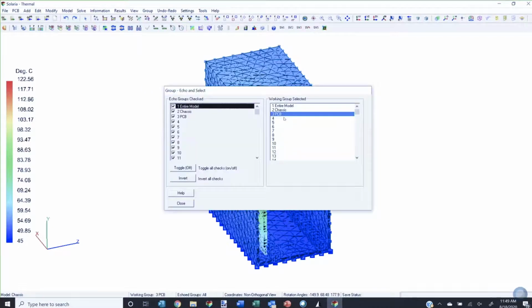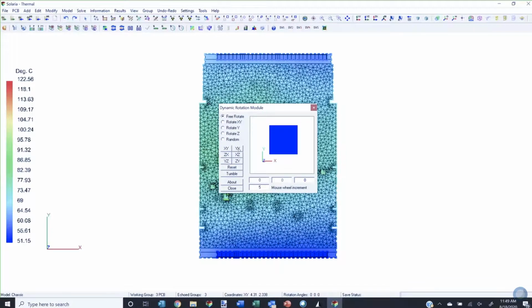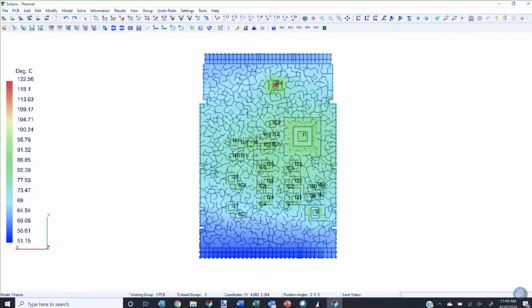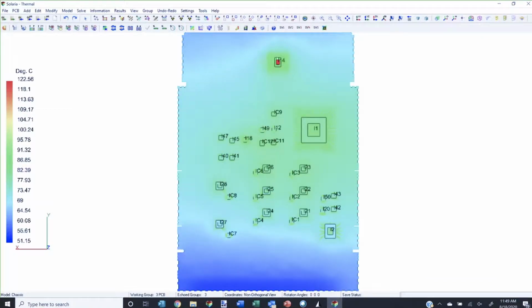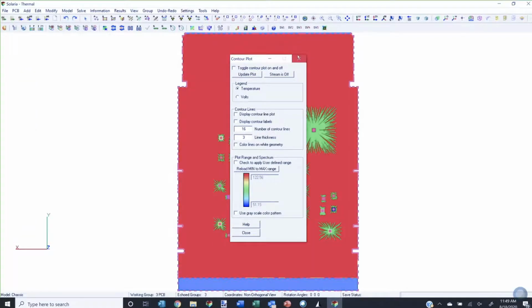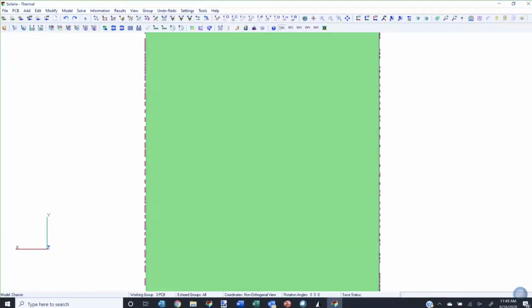Okay. So again, we can go back into results, PCB results, and look at our results in here. We can click on this, bring up our group of our PC board, look at our XY view, and there's our temperatures. Turn off the mesh, and there they are. So each little square, this is the case temperature, and then the center is the junction temperature.